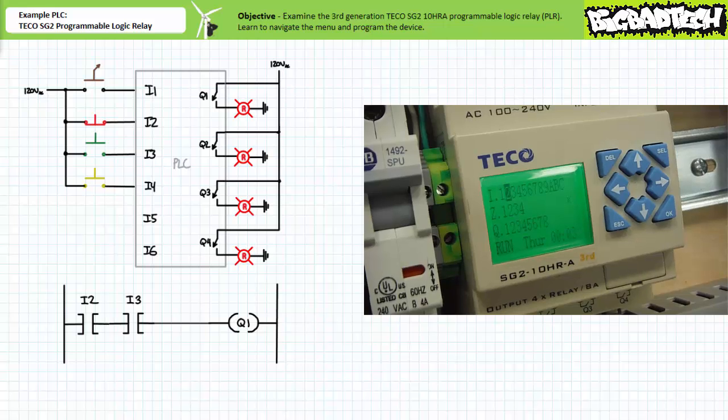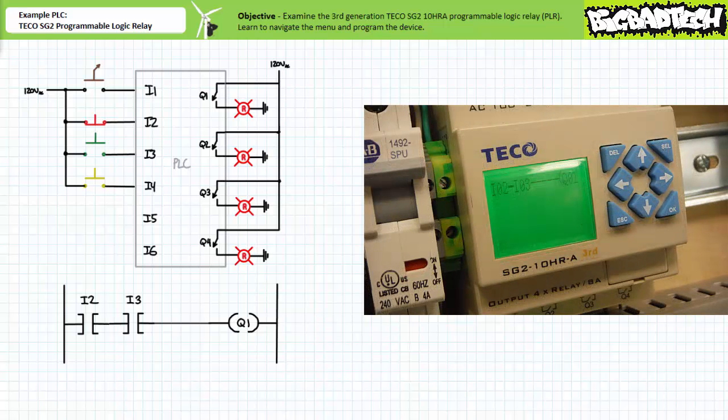While in run mode, an operator can navigate to the ladder entry to monitor an existing program. Press Escape to enter the main menu. Navigate to Ladder and press OK. The ladder entry for a running program, rather than being a means of program entry, now shows the state of the inputs and outputs as manipulated by the operational program stored in memory.